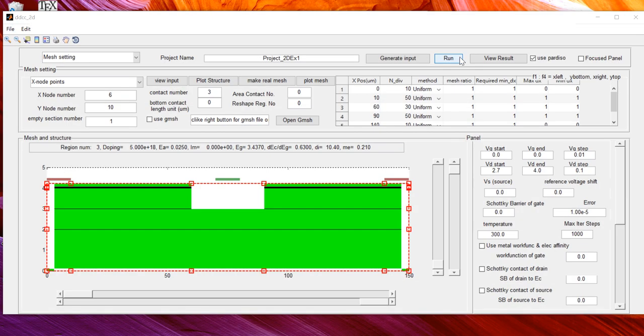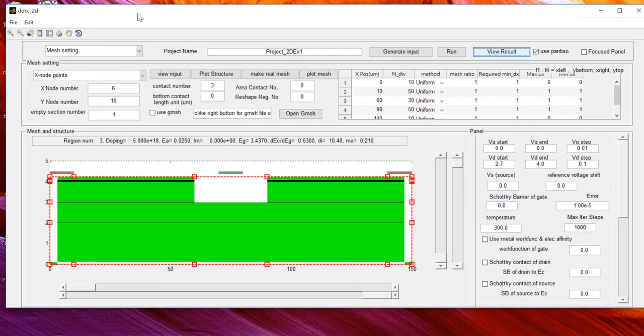If there's no problem, let's set up how to set up an ITO. ITO is very hard to set up because in reality ITO is an N-type layer and P-GaN is a P-type layer. So when they are put together, it forms a tunneling junction, like electron tunneling.